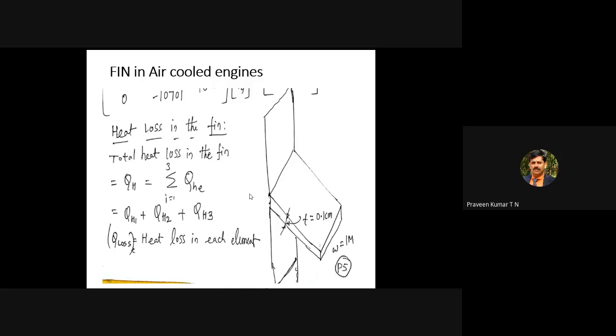In general, the concept of heat transfer, whether it is convective heat transfer or conduction heat transfer, is the heat transfer rate. Even if you come to the conduction equation, we have Q equal to K into delta T into A divided by L. That means your heat transfer rate will increase when the surface area increases.